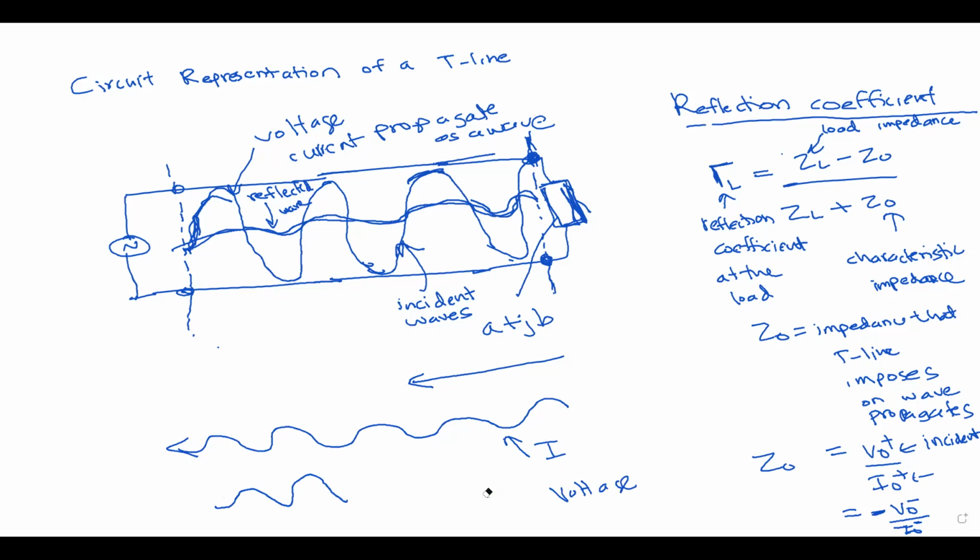That is regarding how we can find the voltage and currents in the reflected directions. They are all moving as waves, and this minus sign is added to represent the minus direction of the wave propagation. You can find the amplitude of the voltage and the amplitude of the current and take the ratio to find the Z naught.